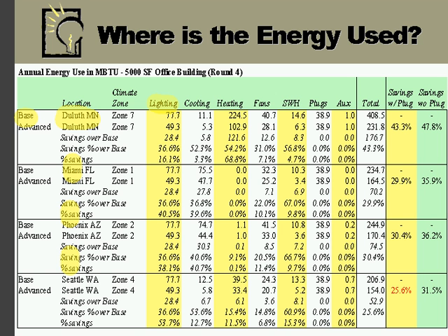Lighting, interestingly enough, doesn't change depending on where you are in the United States. It always stays the same. There's no impact on heating and cooling, where you can see here that the cooling loads change depending on the region you're in. There's very low cooling loads in Duluth, very high cooling loads in Miami. That reverses when you get to the heating loads and so on. Plug loads all stay the same also, because again, those were a consideration that we took out. Originally, when we were first given the charge, we were to include plug loads in the 30% energy savings.